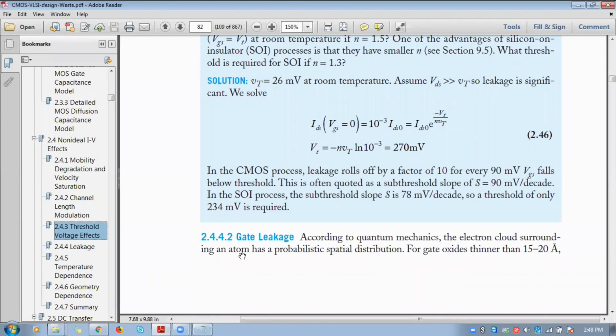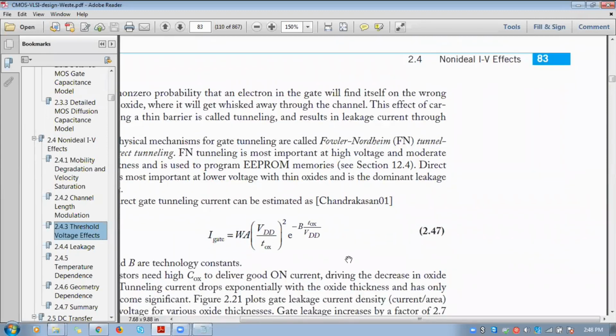So if you increase the silicon dioxide layer thickness, that will result in an increase in threshold voltage. So again, the input voltage has to be high. Then only your gate can attract more minority electrons from the body to the silicon dioxide layer. But if the silicon dioxide layer thickness is high, you have to apply more input voltage to make the inversion happen. So you need to have a trade-off between this tunneling as well as silicon dioxide layer thickness at the time of manufacture.